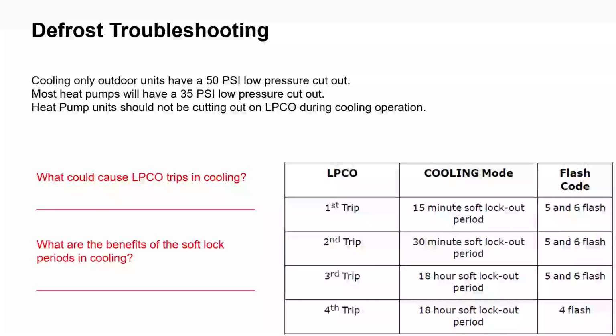Low pressure switch in cooling. Well, a low pressure switch trip in cooling is usually airflow or refrigerant related. Could be low ambient though. If we're running the system in a low ambient cooling situation, we could have some low pressure switch trips.